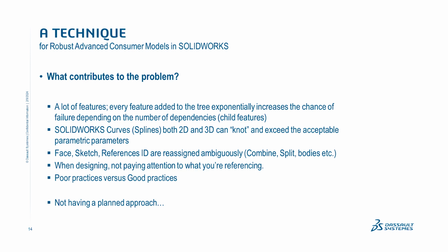From the designer's end, you also need to take special attention of what you're referencing when you build your models. What I mean by that is when you are building a feature midway or late in the tree, and you're referencing a fillet edge or a surface edge, it's really a better practice to find the original source of that surface edge, that is the curve or sketch, and reference it instead of the surface.